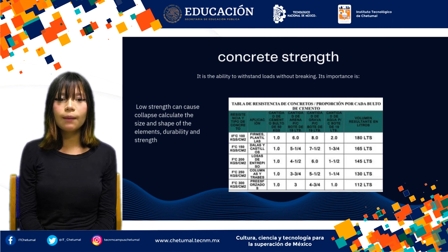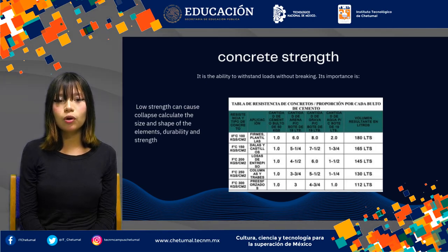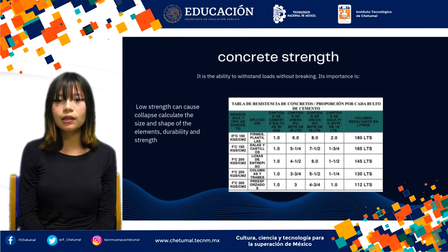Excavation depth. The depth of the trenches depends on the type of soil and the load the foundation will support. A geotechnical study will determine how deep these trenches need to be. Trench cleaning. Once the excavation is complete, the trenches must be cleared of debris or loose material to ensure good adhesion with the foundation. This is important to prevent uneven settlements in the future.